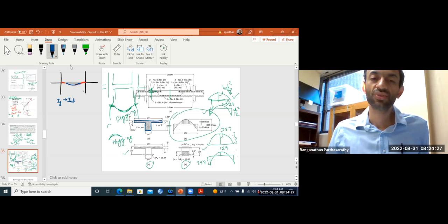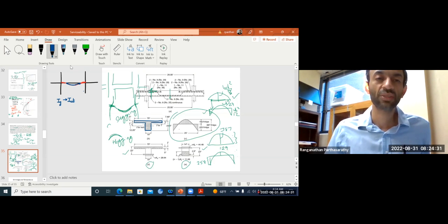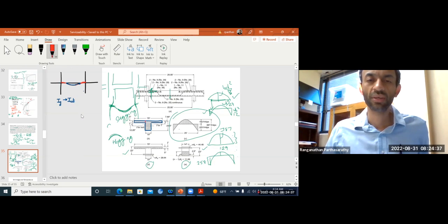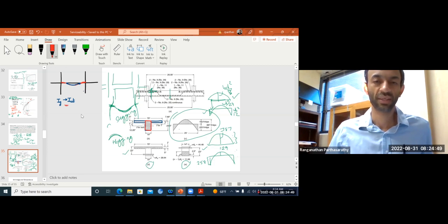Now, for the negative moment region, this flange is under tension. Even though no cracking has started as yet, it is an accepted and better practice to only use this part of it. You don't consider the overhangs when the flange is in tension, even for uncracked transformed, okay?